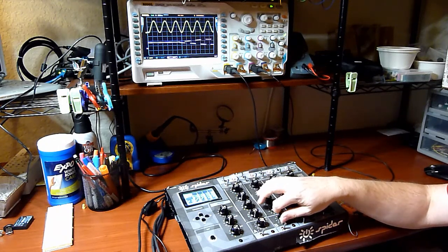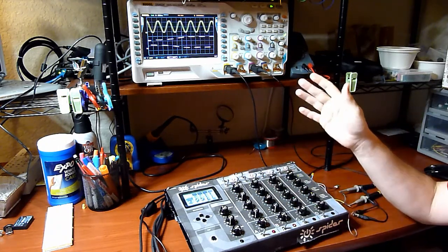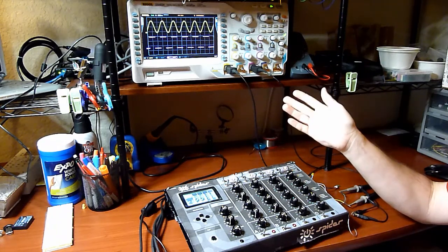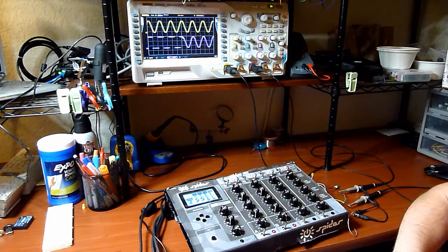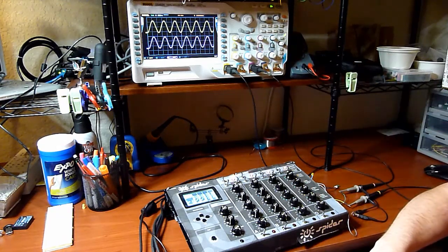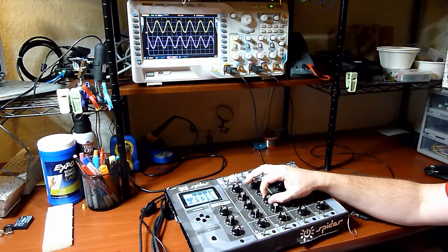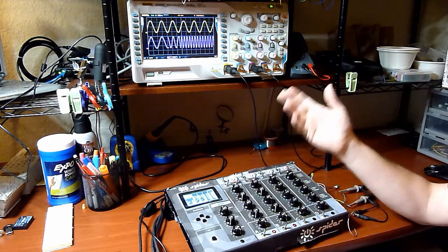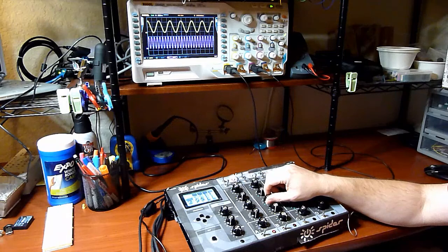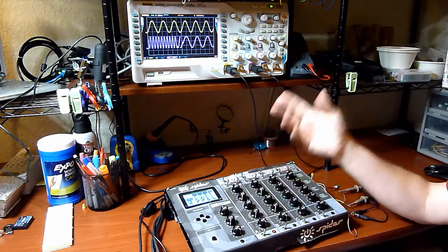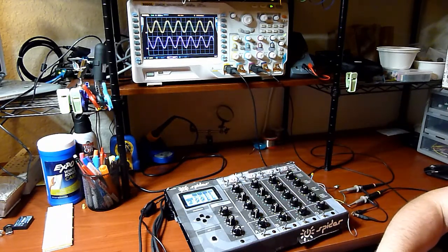So here, if I increase progressively, we can see that I have a different signal, different amplitude, but they are in sync. So if I use sine wave, we can see they are exact. But I have a control on the second channel. Here, for example, I increase the frequency, which is 4 times the frequency of the signal above. But if I come back to the original frequency, they are perfectly synchronized.